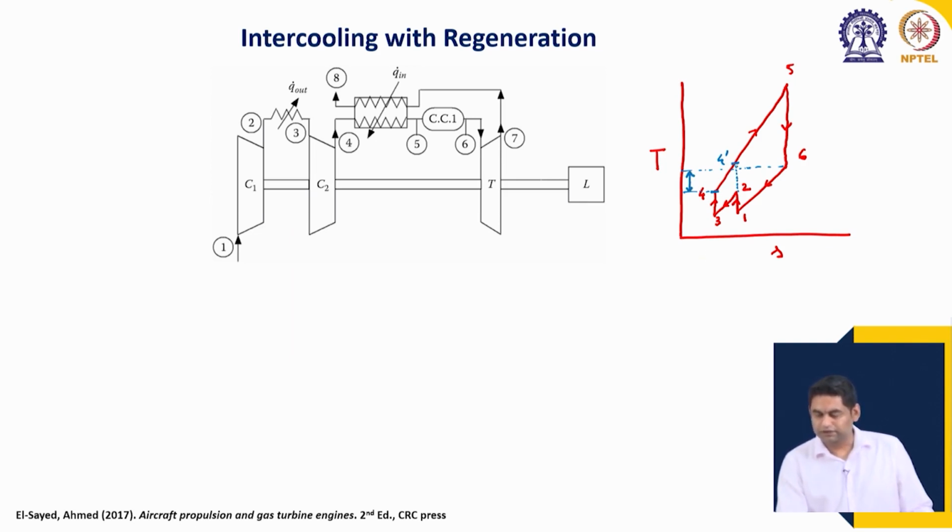As you can see in this example, without the intercooler there was no positive difference at all, and now you have a significant difference, which means that when the intercooler is added, the scope for achieving regeneration is considerably enhanced. So, we get a much higher effect by adding a regenerator. With this idea the regenerative intercooled cycle is designed.